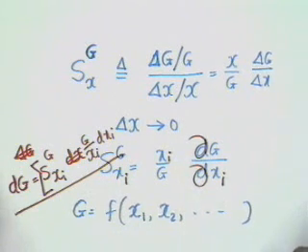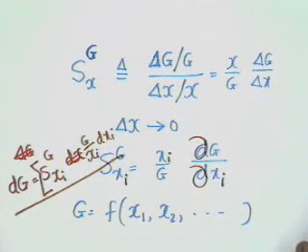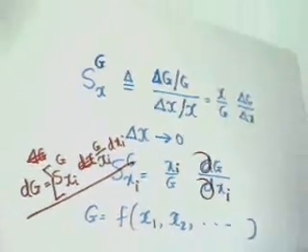Now in the context of our discussion of negative feedback amplifiers, we are going to consider one parameter at a time, and we shall not be concerned with the total change. This of course we have done when we were doing the bias calculations, bias stability, isn't it? We considered three parameters, VBE, ICBO and beta, and we found out the total change.